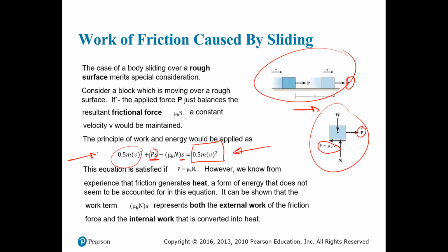Okay, but as you move into your engineering career, you will learn that we actually use all of the different interactions when we are studying systems such as this one. The key takeaway with this is that you always need your free body diagram on your particle so you can see all of the different forces acting on it. And if you use those forces which are causing work in this theory, then you will be able to rewrite the equation as needed, depending on the case.